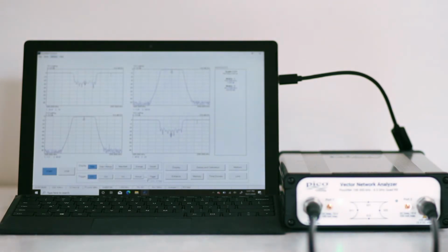To determine the phase, a reference signal is needed. For that reason, two or more receivers are used. Typically, the signals are down-converted in the manner of a superheterodyne radio receiver. The lower frequency signal is measured by means of a quadrature detector. The signal is then displayed and measured. Reflection and transmission data are formatted and interpreted by means of linear and logarithmic sweeps, log displays, polar plots, Smith charts, trace markers, and limit lines. All this makes for some sophisticated instrumentation.